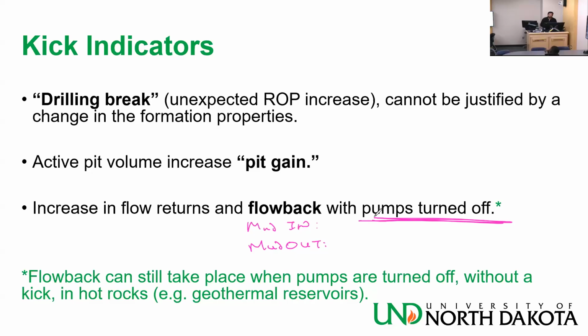So what value do you expect the mud in to show? In this case, I thought I had a kick and I turned my pumps off. So I'm not flowing in, zero GPM. I don't control what flows out, it's the reservoir, the kick in this case. What is my flow out? Bigger than 0 GPM, right?